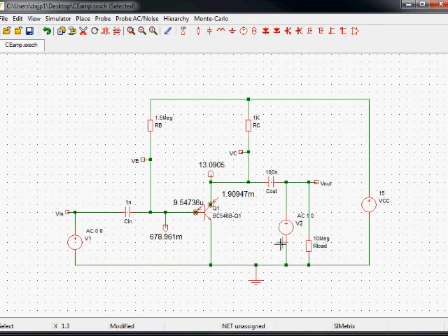So, we're putting a signal into the output now. That's not the normal way that we measure output impedance in a real circuit, but for a simulator it's a very quick and easy way to do it. The output impedance, rather, will just be the voltage that we put onto the output divided by the current flowing back into the circuit, which is the current through Cout.